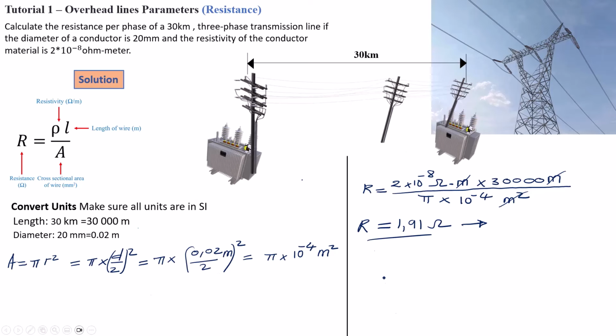So now when you look at it, 1.91 ohm is quite a big resistance if you're going to be transmitting like 2 kiloamps of current. But now remember, this resistance is not over 10 meters. This is over 30 kilometers long of a transmission line that you only going to have a 1.91 resistance across that distance. So basically the amount of power you're going to transmit over this distance versus how much you're going to dissipate, they can actually justify these power losses.